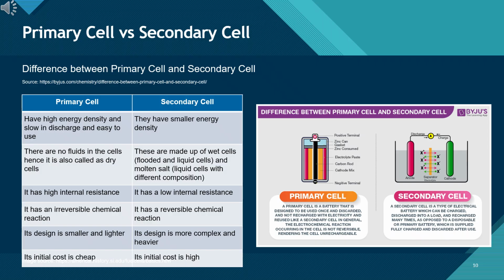In contrast, secondary cells are built around reversible chemical reactions, which allow them to be recharged many times. The design is more complex, with a dedicated anode, cathode, and a separator immersed in liquid or gel electrolyte to enable the back-and-forth movement of ions. This gives secondary cells lower internal resistance, higher current capacity, and the ability to deliver far more energy over their lifetime despite a slightly lower energy density per cycle.